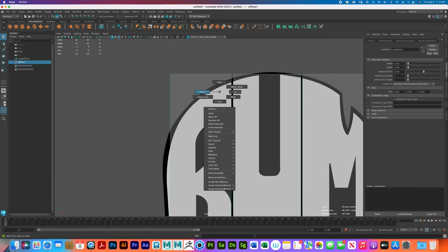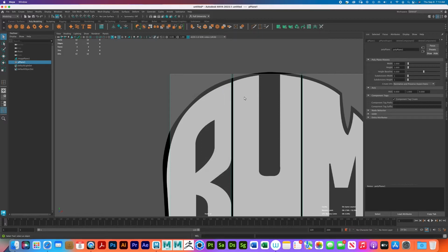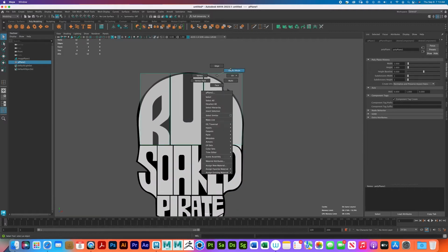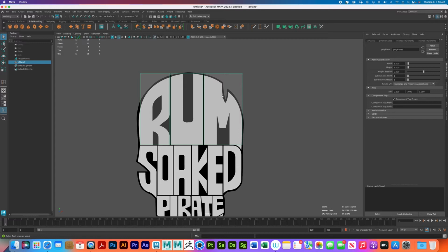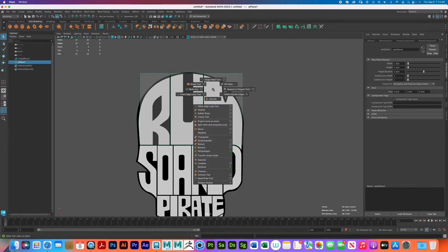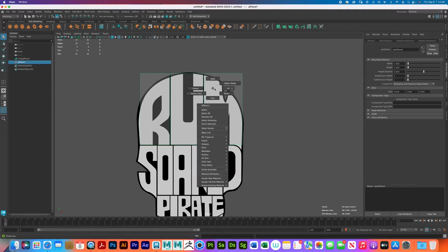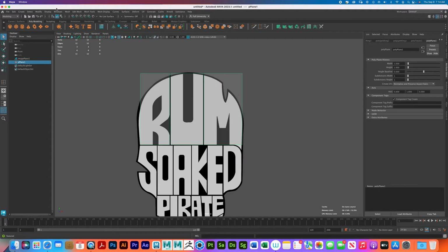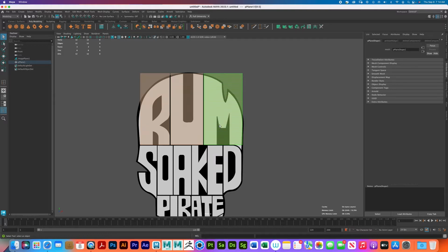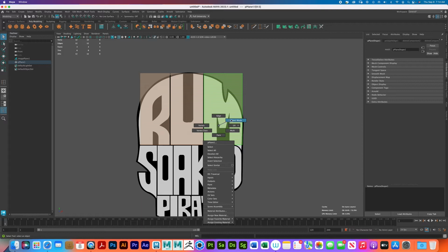So what I'm going to do is click. You know what? Let's separate these, because if I click vertices and they're close to this one, you're going to get confused. How do we do that? With that selected, make sure you're in object mode. Right click or shift right click. So anyway, let's select the faces, shift right click, and choose detach components, then right click to object mode.